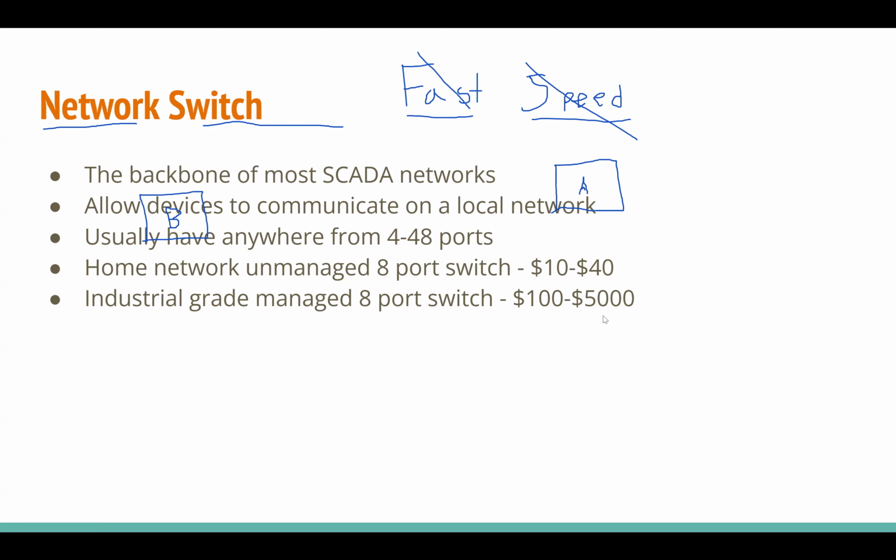And then the last big one is industrial protocol support. We need switches to support certain things. For example, precision timekeeping through PTP is something we utilize. That's a functionality of the switch; it actually has to support that. There are very few switches under like $2,000 that support Precision Time Protocol. So for industrial communications, if we need that, then we need to buy switches that support it, and it can cost a lot of money. So don't be surprised when you buy a switch for your house that's $40 and then you try to buy one for industry and it's $5,000. What's the difference? Those are the differences.